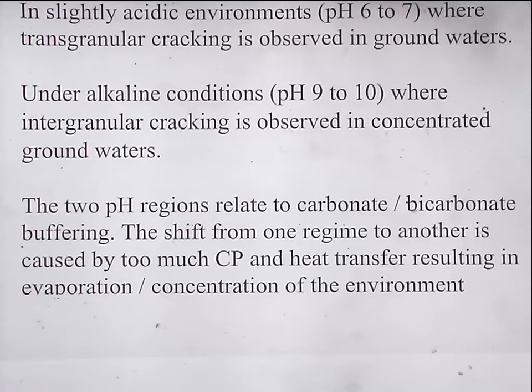These are some sections from tensile specimens after test, just to illustrate what's going on. This is X100, which is one of the higher grade pipeline steels that are beginning to come online. And what we've got is intergranular cracks in the section of the specimen. So we've sliced the specimen. These are individual grains, and you can see the crack is moving around the grains. So that's intergranular failure under one set of conditions.